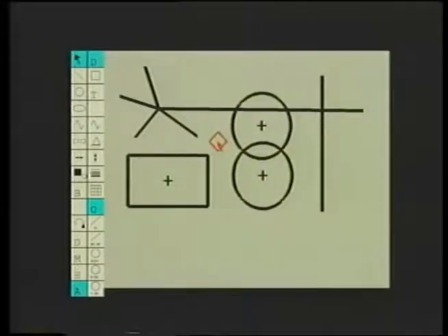To show snapping, feedback lights up the object snapped to with a yellow stripe and changes the cursor's shape depending on whether it is snapped to a point or to an edge. When multiple objects are close to one another, pressing the cycle button selects among them. Snapping is used for all drawing operations such as selecting, dragging, and creating new objects.